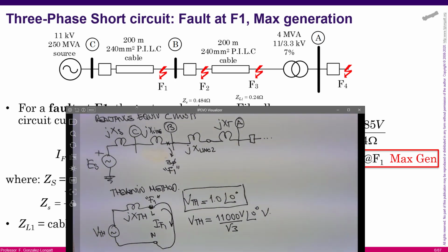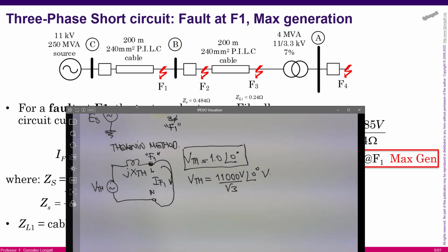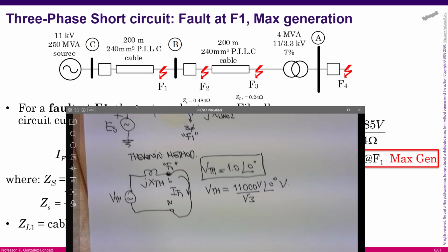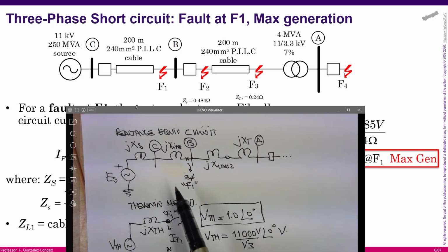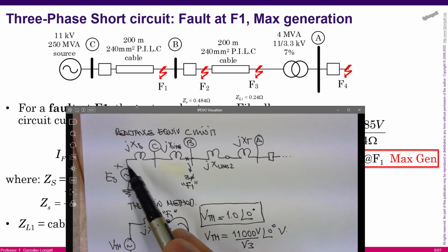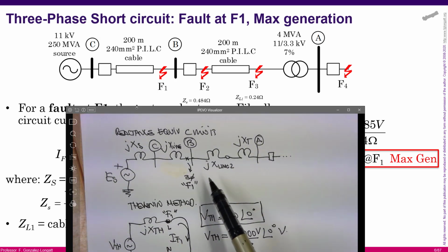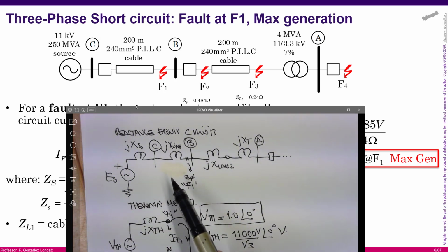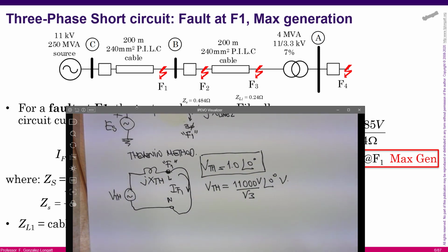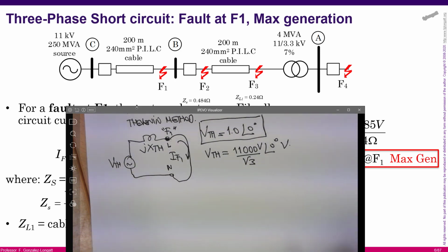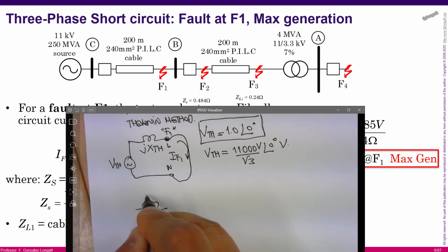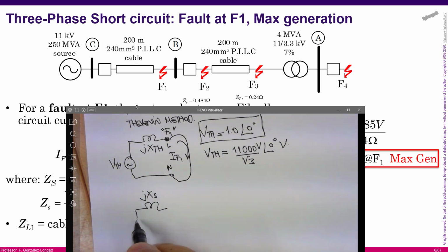Then, what is the next step? Okay, the next step is extremely simple. How do we create the Thevenin equivalent model? What we need to do is switch off this voltage source by using a short circuit that represents voltage equals 0, and calculate the Thevenin equivalent impedance, okay? What I'm trying to say is that now we can use this circuit over here. This is the external source. Here the voltage is off.